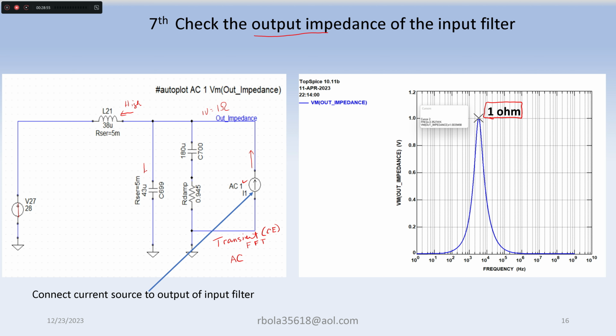No, actually a low impedance. And since this capacitor is much bigger than this one, at least 4 times to 10 times, it is the dominant impedance. So basically this should be kind of like a short.